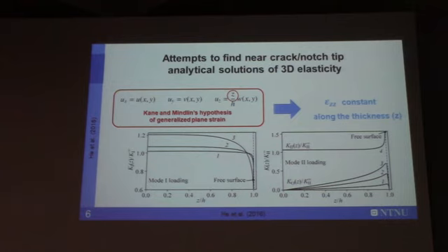But now we know that for crack cases, here we have the normalized stress intensity factors. They vary along the crack front from the mid-plane to the free surface in this way. And for mode 2 or mode 3, here mode 0 is represented as the coupled mode due to 3D effects, but now is not the moment to talk about it. Anyway, now we know that something happens near the free surfaces.